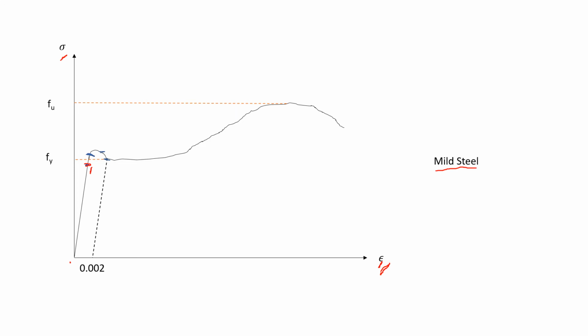And the second point is what? Up to that point is the elastic limit. The elastic limit means that when you release the load at that point, the material will regain its original position. But the difference between those two points is that up to proportionality we have the same proportion of stress and strain, and up to the elastic point that proportion is not valid. It is just the property of regaining its original position. That's why we denote it as the elastic limit.